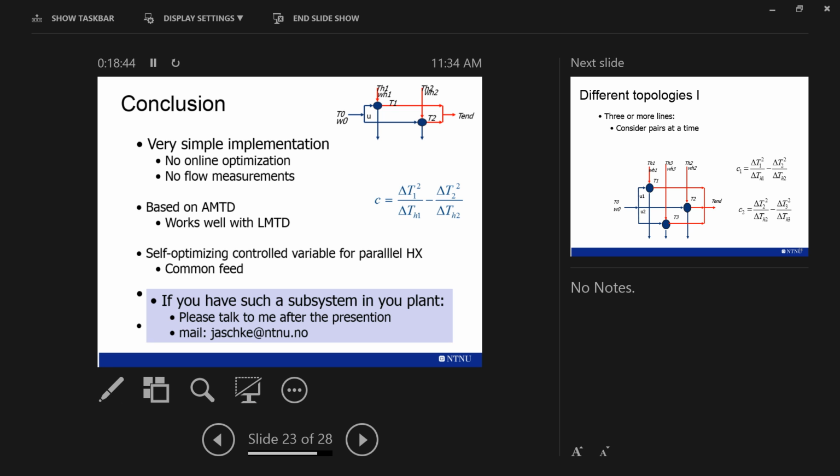But what I'm considering here is you've designed a heat exchanger network for me, and you already did that. I just use what I get. And actually, if you operate the system, then typically, in most cases, you operate at a completely different point because these constraints of the minimum temperature differences are not active anymore. So this deals with operation of heat exchanger networks and not with design. You could probably also use it as a kind of shortcut method for designing networks like this, or to add it as a constraint. But I didn't do anything with the minimum temperature differences.